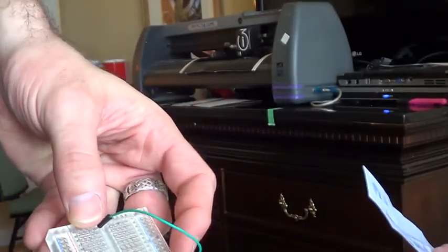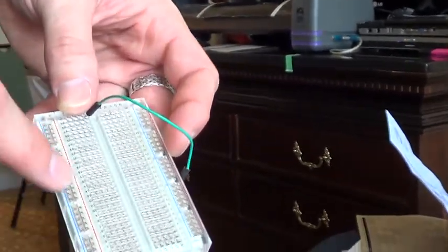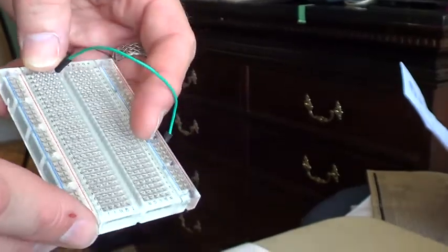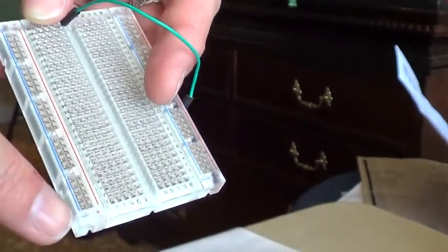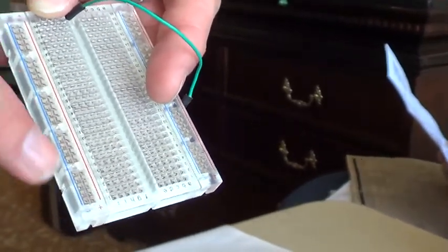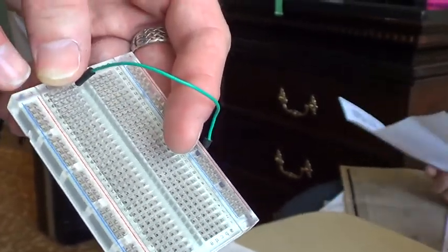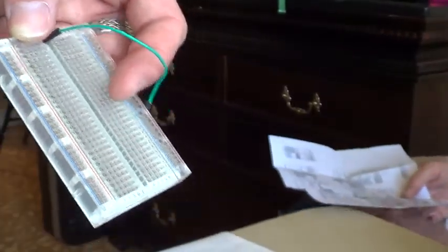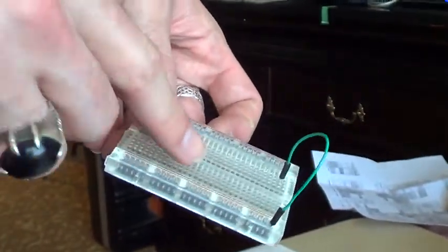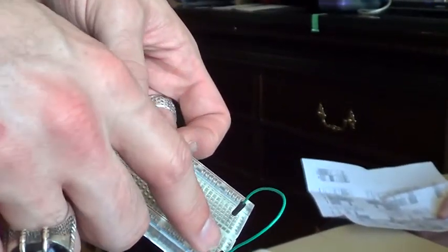These ones on the side, you probably won't deal with these much, but they're called a power bus, basically. There's a negative and a positive. These entire columns are connected electrically, but not to each other. So these two columns are not connected. But basically, that allows you to bring in power from various parts on the board. You can plug in your negative over here and your positive over here, but still have it available way on the side of the board.